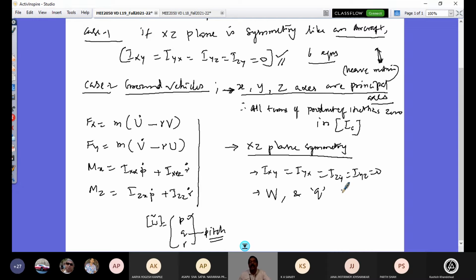So there won't be any pitch. There will be no roll. There will be no lateral. All these are not going to be there. It's only translation, you can say. But still, it's valid to have roll and yaw, because I want my ground vehicle degrees of freedom reduced to 4 from 6. So what are the 4 degrees of freedom? Now two translations, forward motion and lateral motion, and then you have two angular velocities.